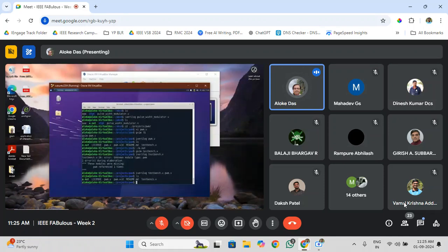This is the output simulator from iverilog. Just remember, the output simulator comes out as a.out. Here I ran a.out, nothing came out. See, no output. But if I compile the test bench and the design under test together, and then run a.out, then it is simulated.